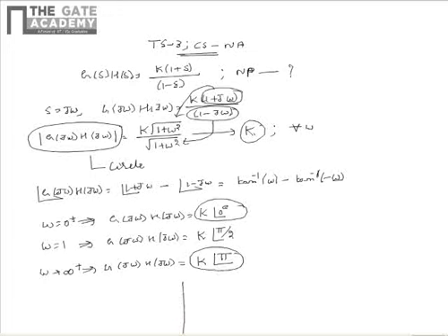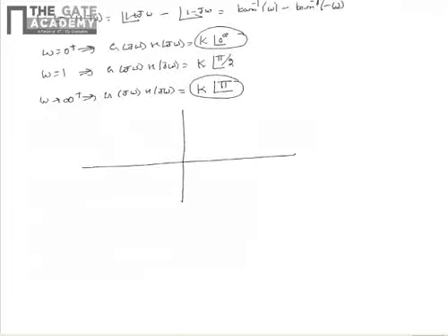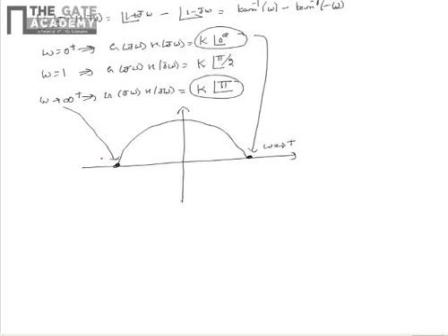So upon plotting the same in the Nyquist plane, that is G(jω)H(jω) plane, ω equal to 0+ corresponds to this point and ω equal to infinity+ corresponds to this point. And we also see that the Nyquist plot is a circle because the magnitude is remaining constant at K. So this is the variation of the plot from ω equal to 0+ to infinity+.